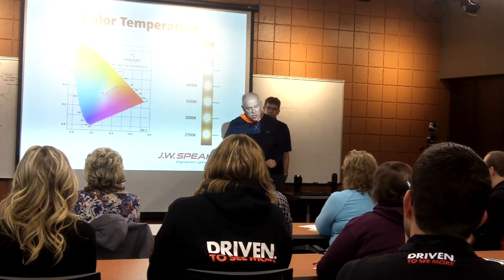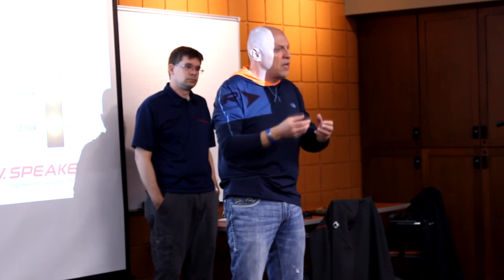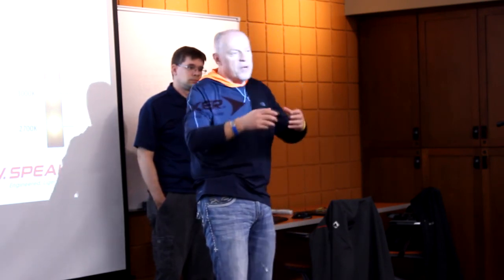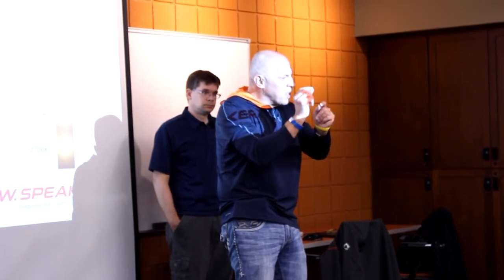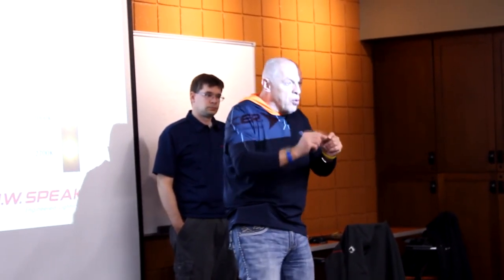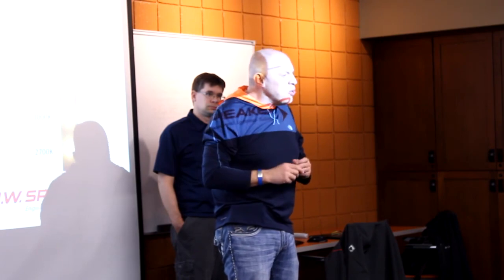Now, depending on the application, color temperature is very important. If you are on a road with a somewhat gray pavement, tarmac, whatever it is, LED is a very nice source. But if you are on a very yellow surface or a very black surface, because of that color temperature and blue peaking in LED, you are not going to see very well.